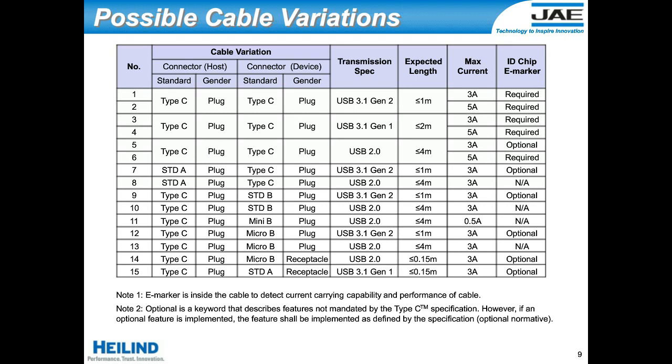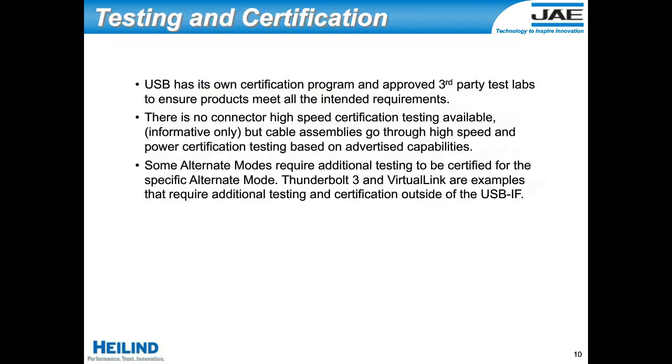amps. Early on, there was a lot of news about devices that were overheating or being permanently damaged because they were being plugged into non-compliant plugs, because some of these pull-up and pull-down resistors were not implemented correctly. And so there was some initial confusion with that, but at this point, people have become more aware of the spec, and most of the cables out in the market right now should have the proper pull-up and pull-down resistors that identify how much current the device can actually pull.